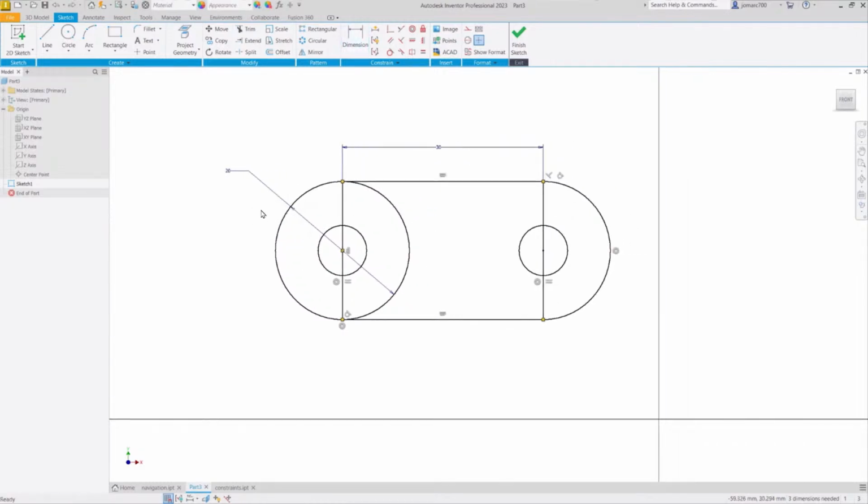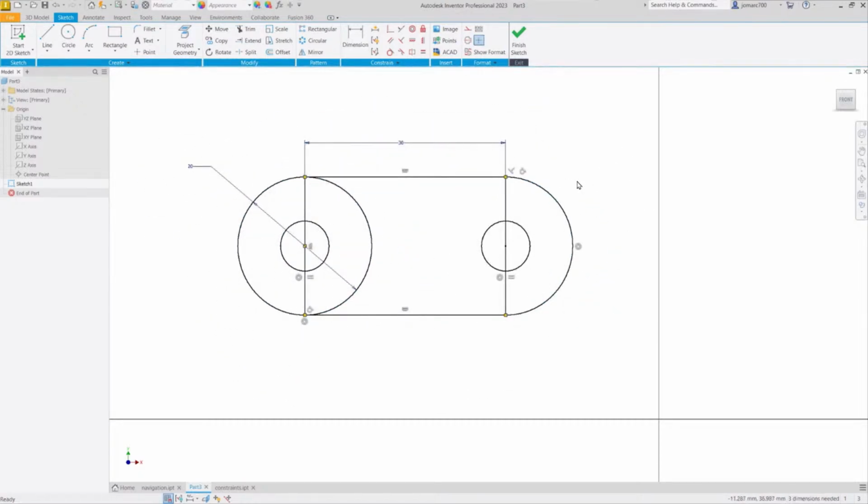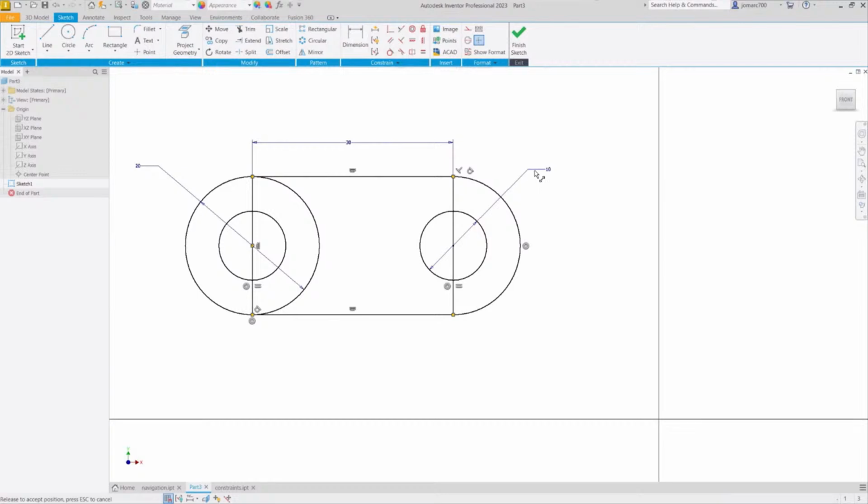Let's try to resize our geometry. Let me grab this circle and try to move this. Let's try to move this circle. Notice this one needs to be defined. Hitting D for dimension. Selecting this circle. Left click here. Target diameter to be 10. Selecting the green check mark. Hitting escape. Inspecting.